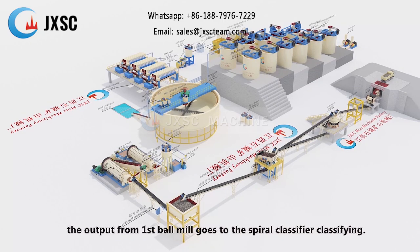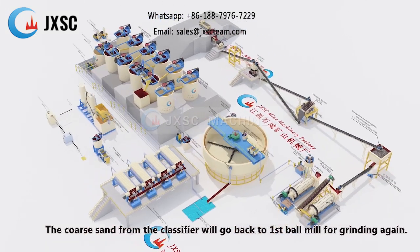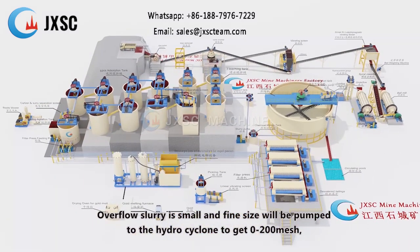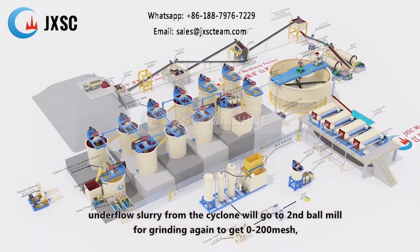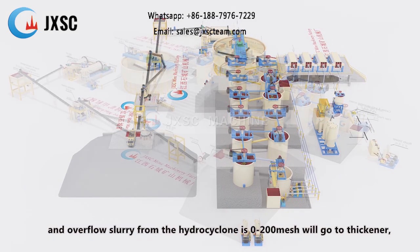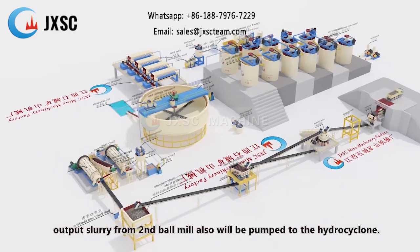The output from the first ball mill goes to the spiral classifier for classifying. The coarse sand from the classifier will go back to the first ball mill for grinding again. Overflow slurry, which is small and fine, will be pumped to the hydrocyclone to get 0 to 200 mesh. Underflow slurry from the cyclone will go to the second ball mill for grinding again to get 0 to 200 mesh, and overflow slurry from the hydrocyclone, which is 0 to 200 mesh, will go to the thickener. Output slurry from the second ball mill will also be pumped to the hydrocyclone.